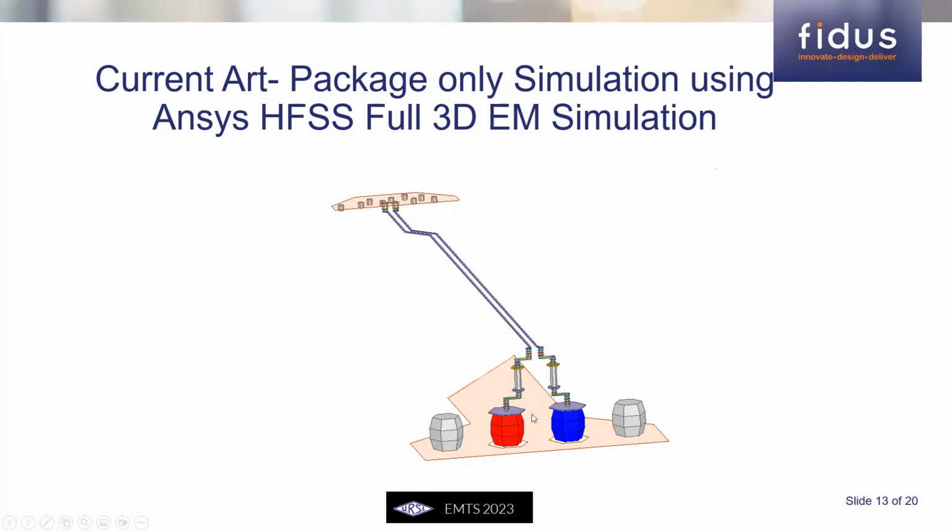The package eventually needs to get integrated with the PCB. The PCB itself would have pads that will connect to the balls. So at the interface between the package and the PCB, there is a discontinuity. If you notice how the ports are defined, the ports on the die bumps are very small. Typically, they are like 35 microns in radius, maybe 90 microns in height. For the frequencies we deal with, it is acceptable to define the port on a die bump without sacrificing the accuracy too much. Otherwise, it gets extremely complicated to have a port within the die. So this is acceptable because the structure is small.